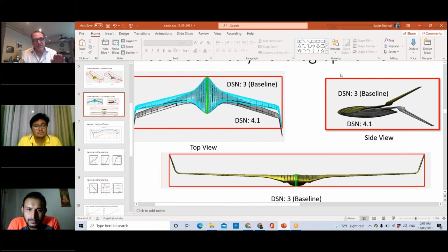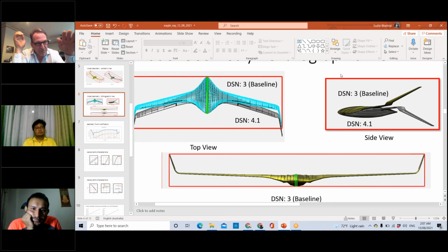Got it. So it was kind of mushing. It was probably doing an easy pitch up that was increasing drag, and your flight path went down. You weren't seeing a wing drop at the stall. It was just kind of mushy and tended to depart in a descent. So it sounds like it wasn't diving so much as just mushing. It was nosing up relative to the airflow, but its flight path was then going down.